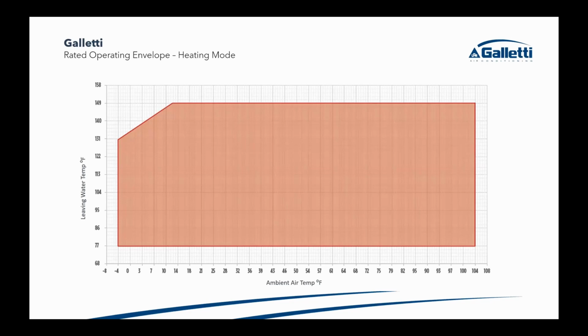there are applications where we're doing a staged approach, where we operate the unit as often as we can, and then unless you upgrade your coils or your existing heat emitters, you would just have a changeover temperature, similar to what George and we were talking about earlier. Residentially, you have that commonly in Massachusetts. So it just shows the 149 down to about 12 degrees, and then the -4 producing 131.